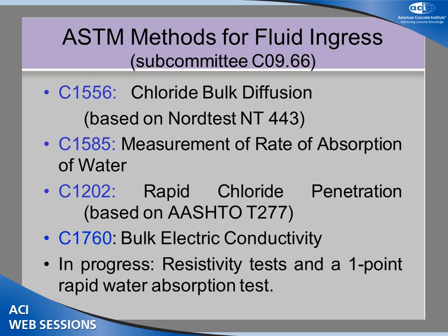And just in the last 6 months, we've standardized C1760, which is a quick bulk electric conductivity test based on using the C1202 equipment. Where you take a 1-minute measurement and just take the current and measure conductivity, conductivity being the inverse of resistivity. Sort of leads us to where I'm going with this talk.